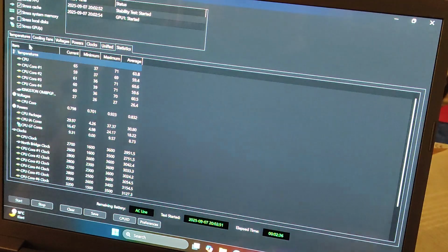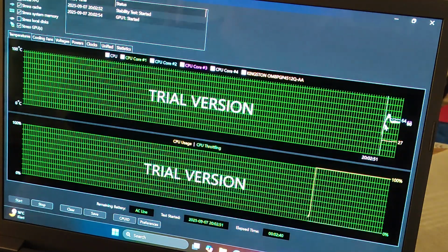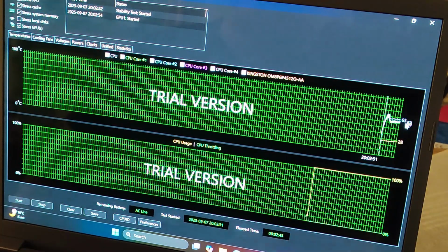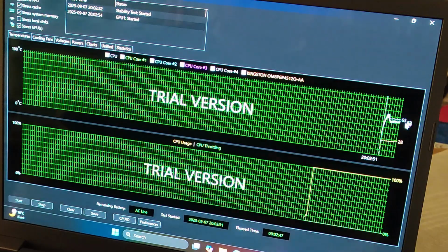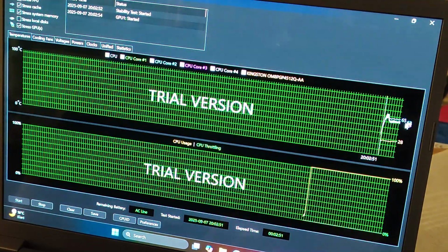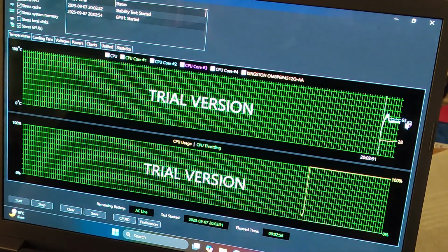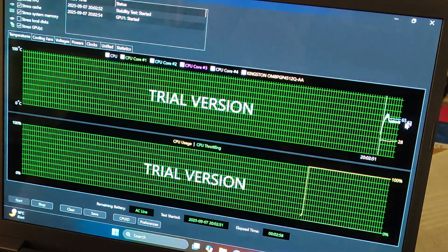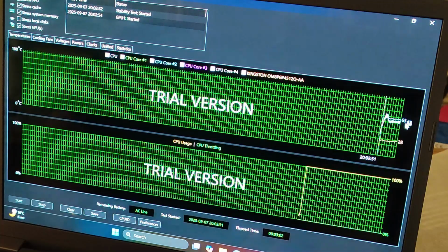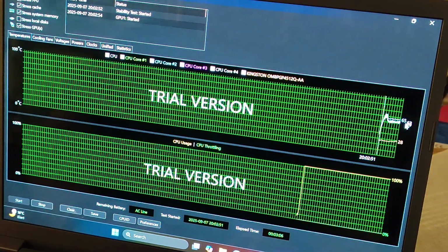So we can see that here we got this little bump in the beginning, and then the fans ramped up and the temperatures went down. So yeah, about 10 watt difference. So 55 watts or so, and I think the power brick is rated at 65 watts. So we're starting to push our luck on the power brick a bit as well.